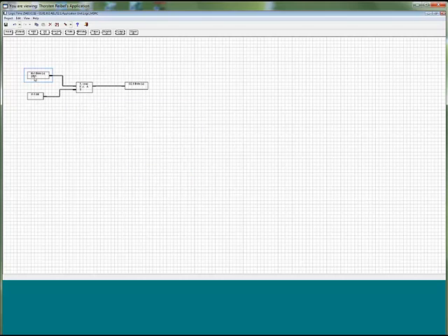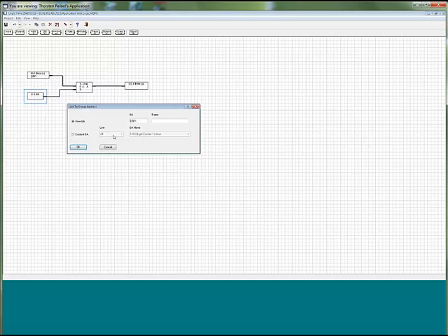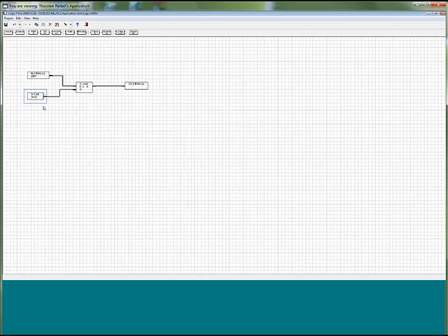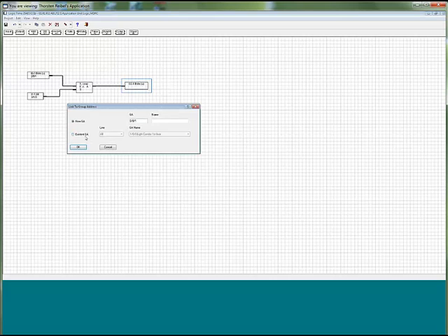And then you will see my input element here is now linked with this group address, and I can do the same with my output, and for example here with my control input group address. This must be a 1-bit group address, link to group address, existing group address, like for example absence. Okay, and now when I'm absent, let's link it here to another group address, for example.